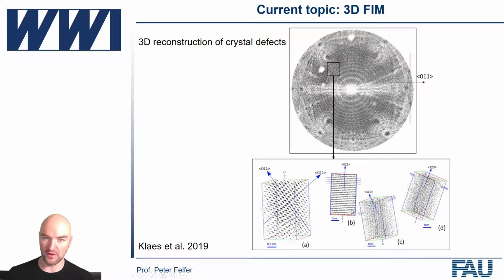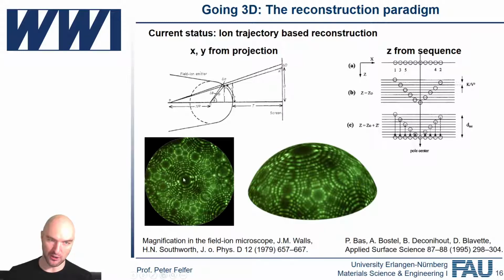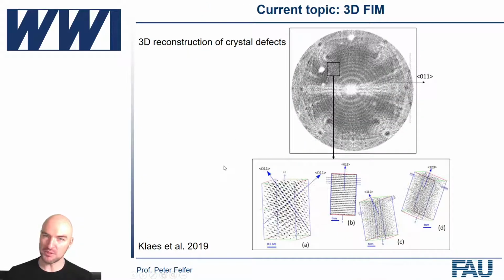The colleagues in Rouen have really perfected that very, very well. And then you can actually get an image. If you think about it, here you actually get a lot of signal, tens of thousands of ions evaporating, giving you the image of one individual ion. So if you evaporate through a sample, a lot of atoms will be visible at least once. And you get a lot of information from that. And you can do a 3D reconstruction, and you can allocate the individual atoms in 3D and have a 3D reconstruction with 100% where you see each individual atom, at least in some sub-volume of your sample.